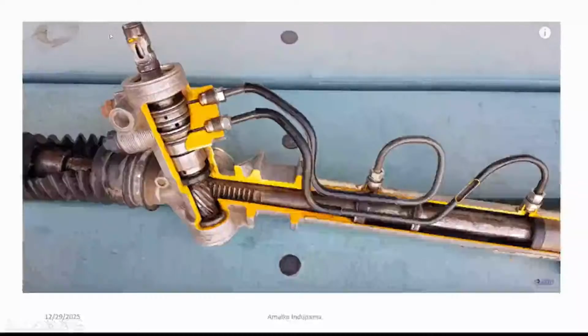Based on the steering effort provided by the driver, this spool valve rotates with the limiting of the torsion bar provided here. Then based on that, the fluid that comes from the pump will be directed to this power cylinder, right? Just power cylinder. Any questions up to now?